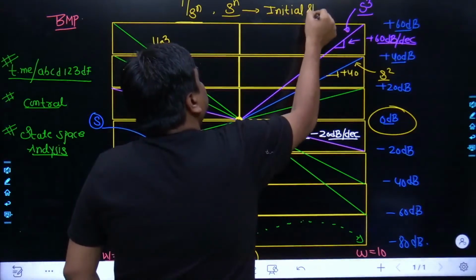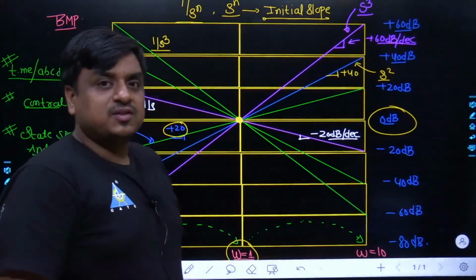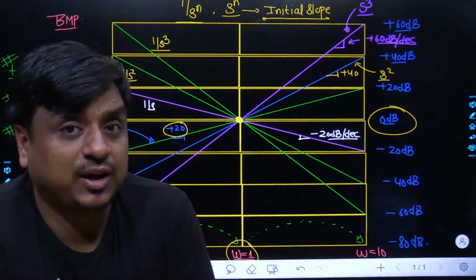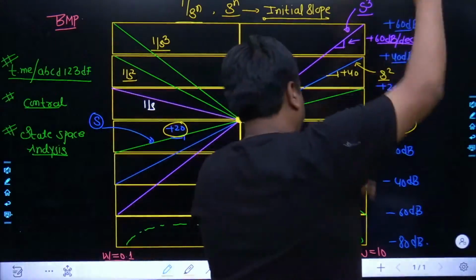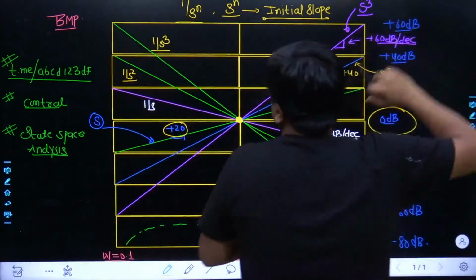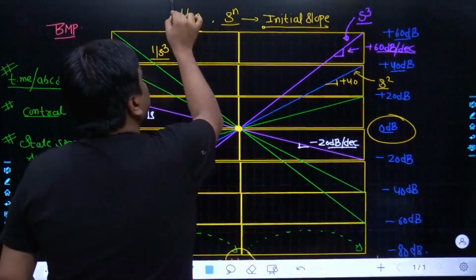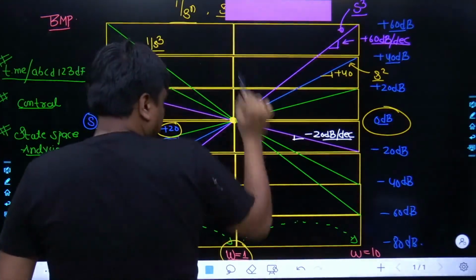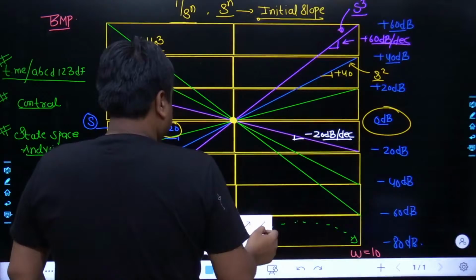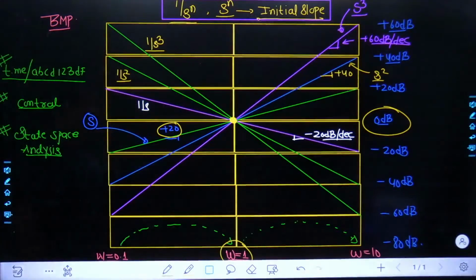So, because of these factors, the slope you have got on the Bode plot would start from which operating frequency? You start from any of the lowest operating frequencies, there also you would have the impact of this factor. And even if you go towards a higher operating frequency, like omega equal to 10, 100, 1000, maybe 10,000, still the slope would be prevalent. So one of the important conclusions we can bring out of this is that this factor is a very crucial factor, and this factor has its impact from start till last. So probably you must have a little bit of an idea about this factor.